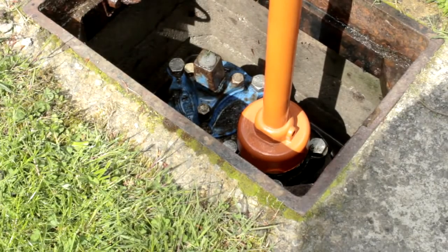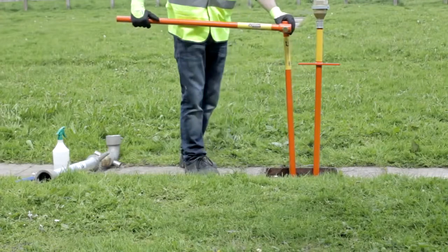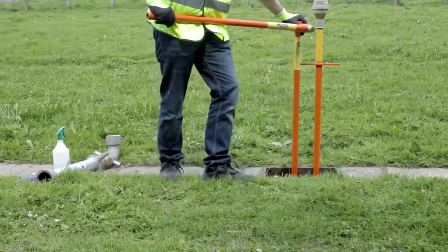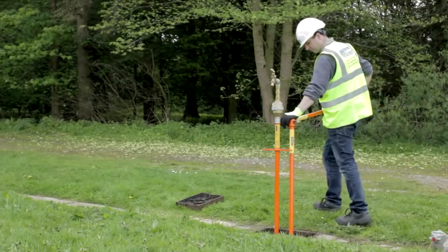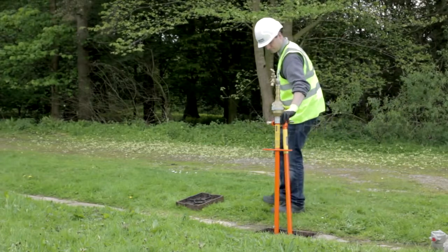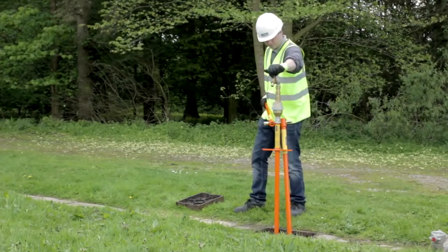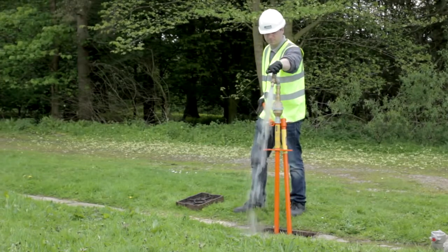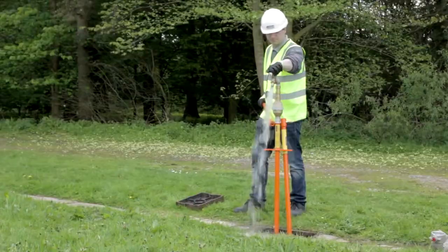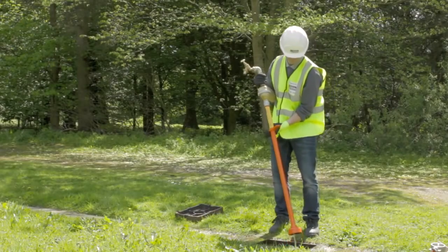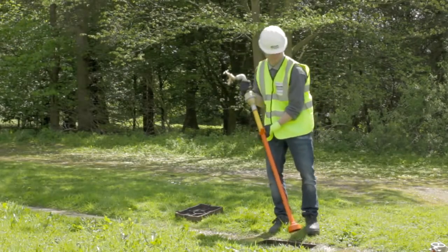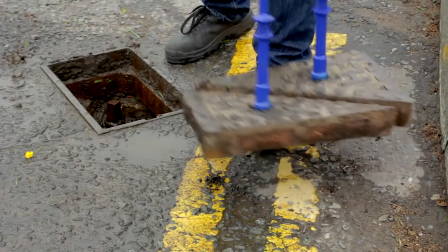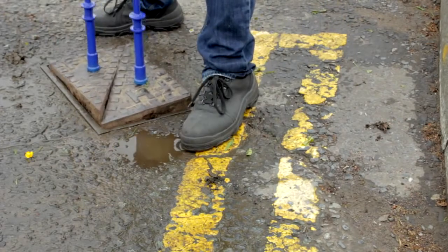Now carefully open the hydrant using the method shown. Never fully open the hydrant, as it will obtain sufficient water without doing this and will minimise any chance of discoloration. Once you have finished using your standpipe, you must replace the lid and leave the site tidy and remove any debris from your activities.